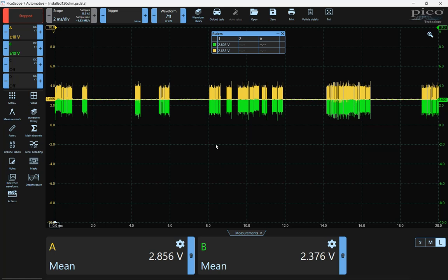And so, yes, it came with active termination. A couple of years later, that same machine would have come with passive termination. Pretty much all those controllers are the same. The only difference is instead of 4-wire quad CAN wire, it's going to just have the 2-wire twisted pair like most truck techs are used to seeing.